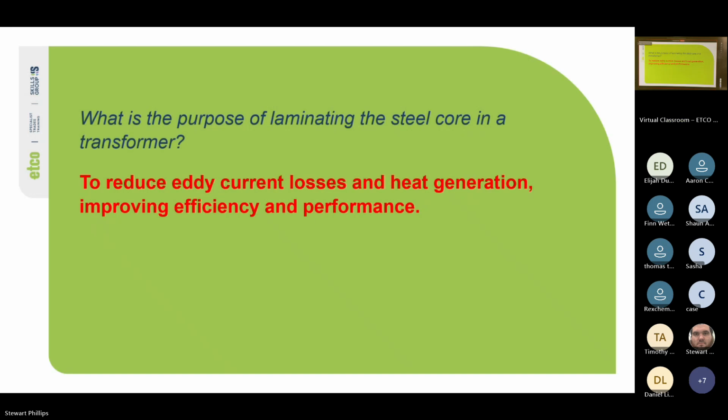Hysteresis. Yep, it has less reluctance, or it is what we consider magnetically soft. Magnetically soft means it is easier for us to magnetize it versus regular steel. So the silicon isn't the insulation. It's more that we infuse the steel with silicon. Okay.